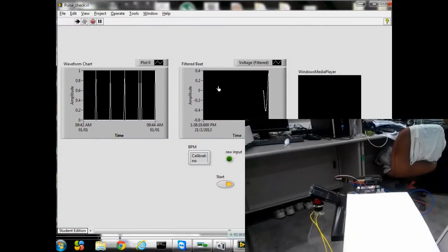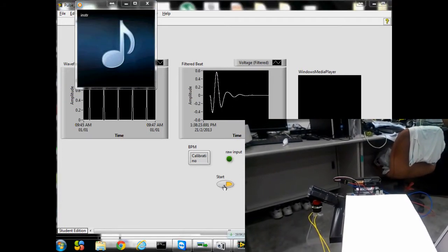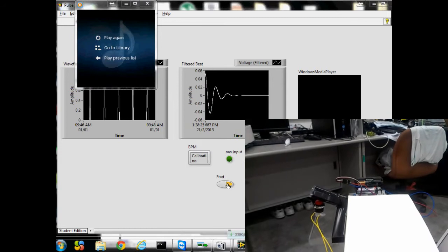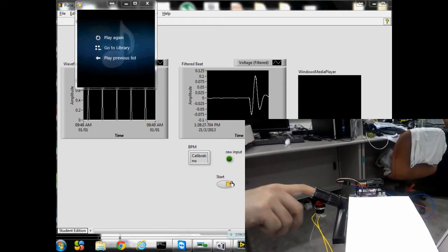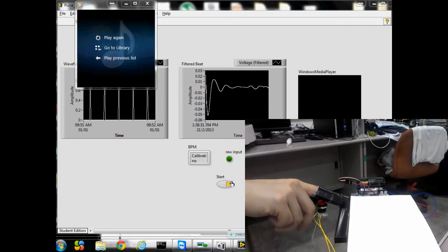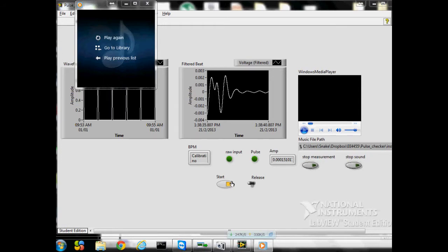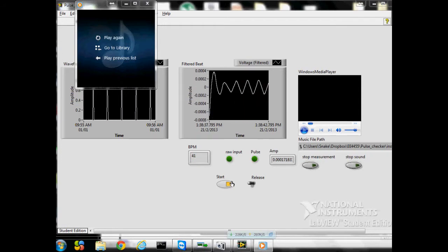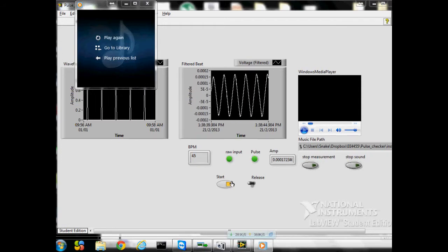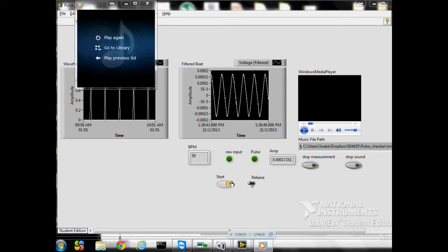When the robot reaches the destination, it talks to the patient by text input. I use the Microsoft text-to-speech converter to get the speech, and then use the ActiveX control in LabVIEW to generate sound. By now, the patient has already put his finger in the sensor. It will take some time to get a stable output, as the averaging function takes time to sample correctly.